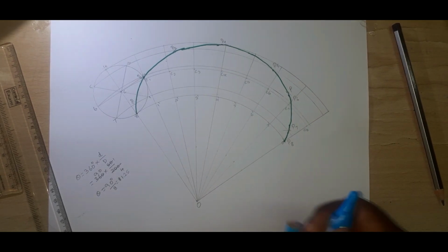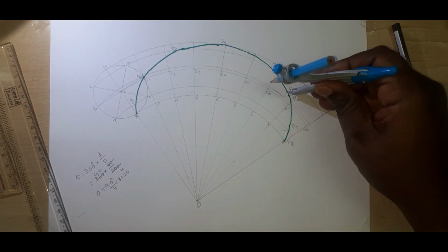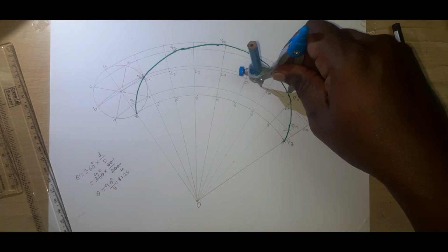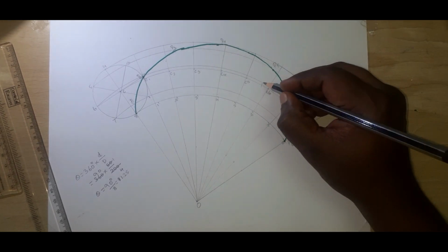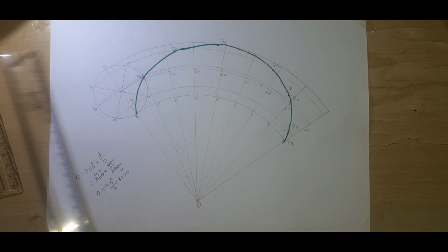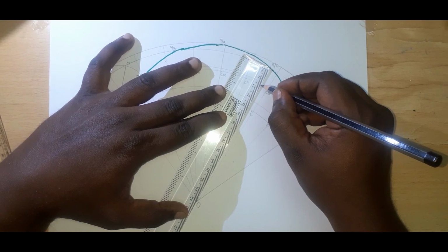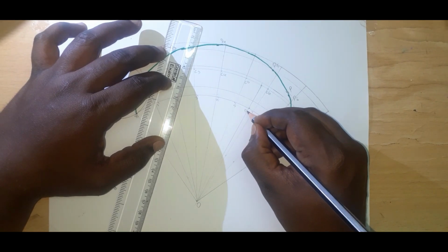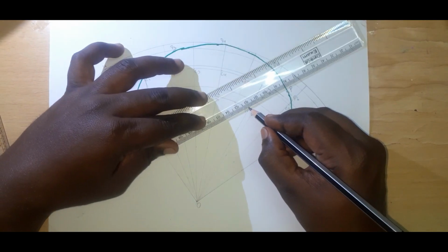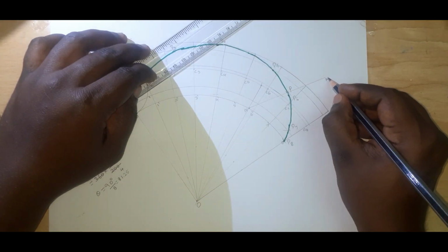Now we know the dimension here, the radius is 25 mm. For this 25 mm, I am going to make an arc on the center line, not any other way. On the center line I am going to make it, because there are two lines and confusion will be there. So the center line. Now I am connecting these two. Okay, here it will be crossed. This point will be called N, and now you can join these two and extend it. This is NM, that is the normal.